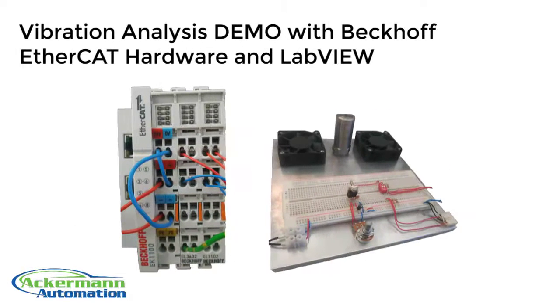In this small demonstration we show the usage of our EtherCAT library for LabVIEW for vibration analysis applications. We use the Beckhoff EL3632 EtherCAT terminal to measure IEPE sensor data and turn it into a frequency spectrum.